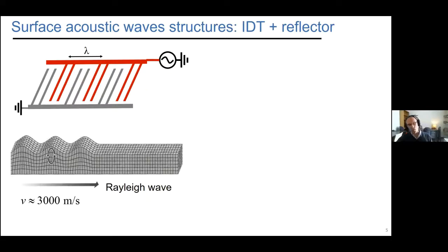If you want to make a multi-mode cavity, if you want to confine these waves, you need to make a reflector. The issue is a very highly reflective element on the surface will scatter waves not only back where they came from, but also down into the bulk. And so we use a distributed array of weakly reflective elements, where none of these elements scatter strongly to the bulk. And in a narrow frequency range, the incident radiation is completely reflected because each individual reflection adds coherently.